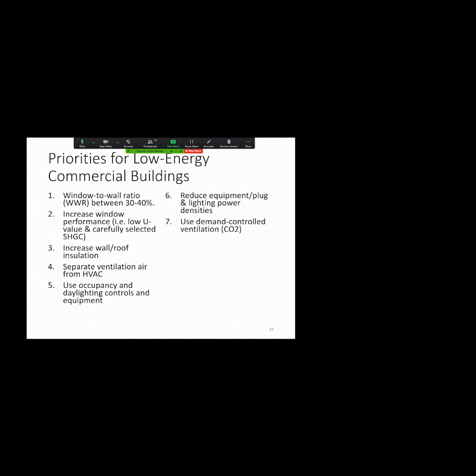And there are sensors in some of these more complex HVAC systems that will measure the amount of CO2 that's in the air and then introduce ventilation air when it gets above the limit where we want it set. We want to improve HVAC efficiency and use heat recovery. So when we do exhaust the air, when we need ventilation air, we need more fresh air coming in, we've already paid to condition the air that's in that building.